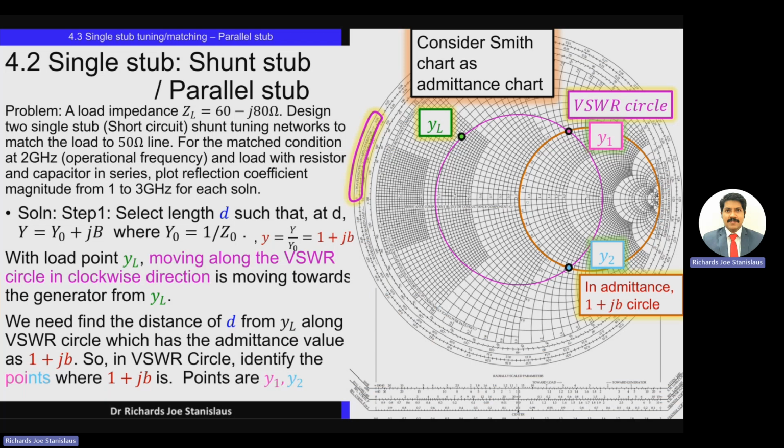So for the reference point, take the center point, which is the characteristic impedance Z0, and the load point as another reference. Connect these two and extend the line. Use a scale, mark and extend the line starting from the center of the Smith chart to the load and extending outwards. Now, in the wavelengths toward generator scale, whatever value is there, you mark it, and that will correspond to the load's location. That is the reference location of the load.